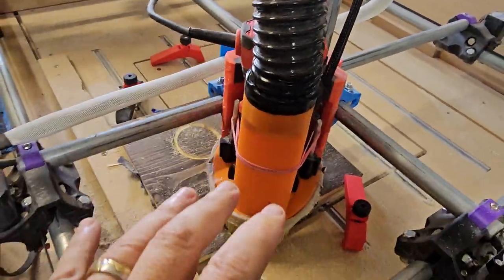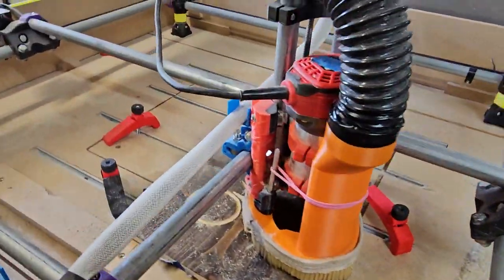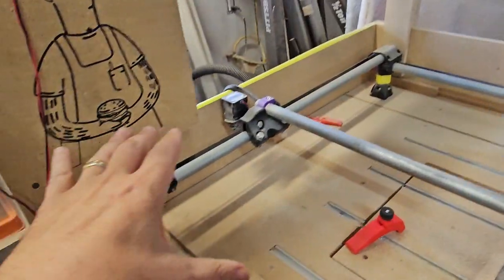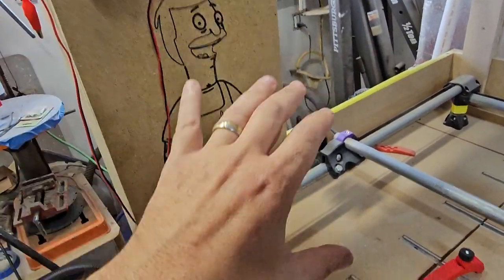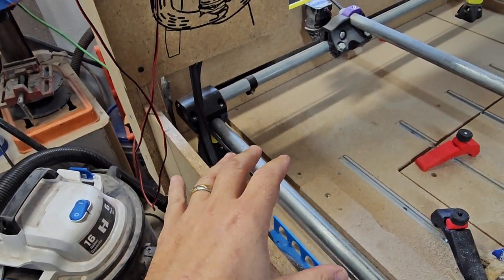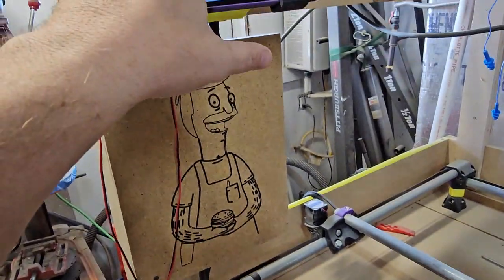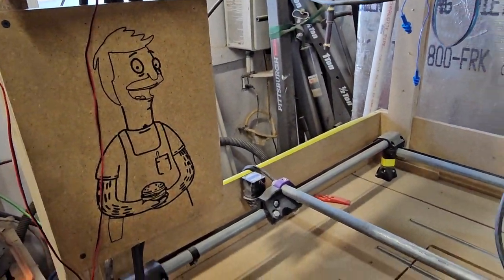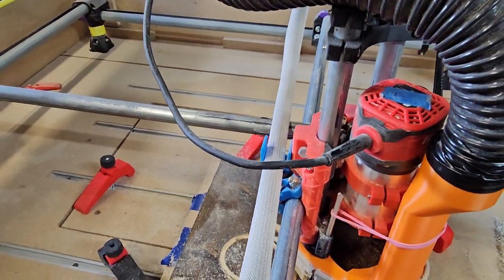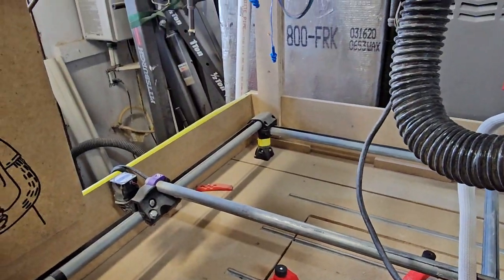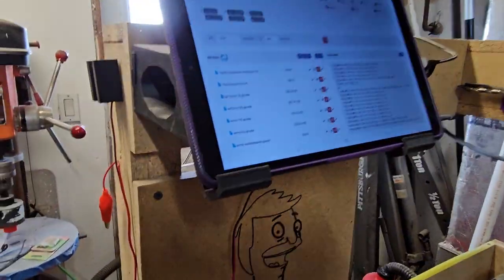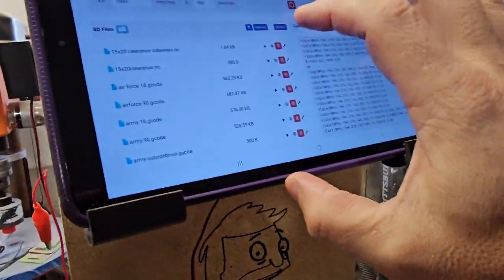So physically, the machine is now set up to cut. My router is turned on physically. My dust collection's turned on. Everything is controlled by the software on mine. I've got a relay underneath the table basically that through G-code, it tells it turn on, closes it, then everything powers up and it will just start cutting all by itself. Once I do that, it's going to get noisy in here, so I'm not going to do it till the absolute last second here. Then, so physically we're ready to go.